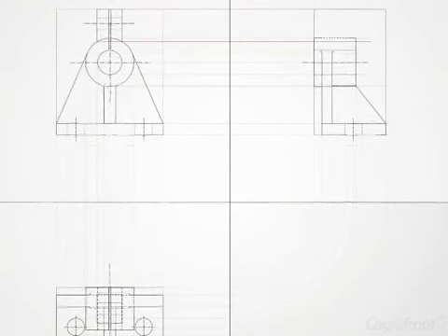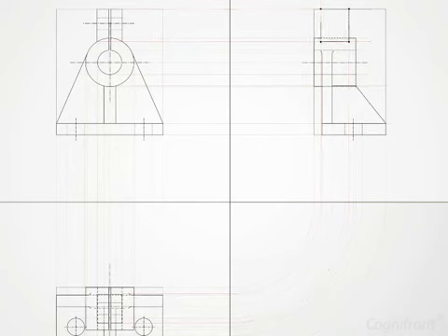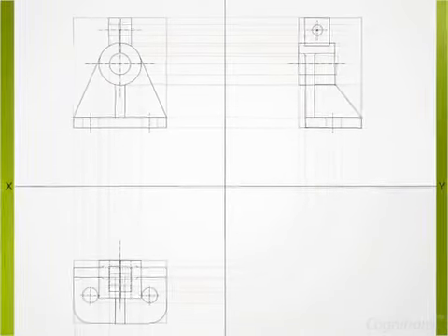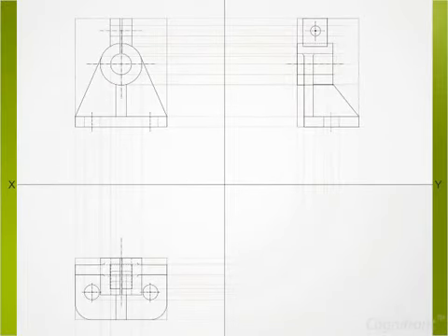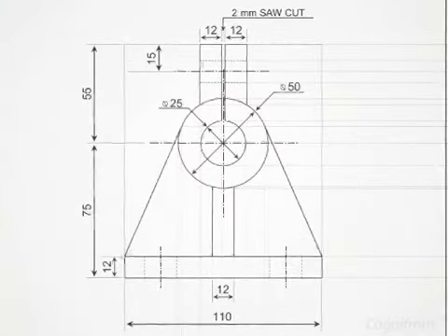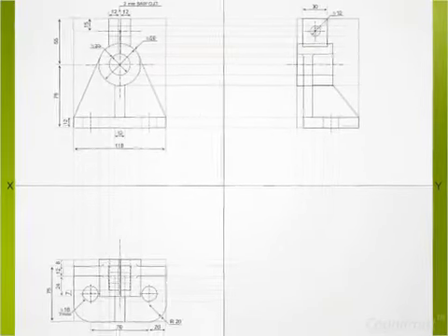Next, the block on the top of cylinder should be generated. Also, observe that we will have to show hole that goes through this block. So here we are with all the necessary details sketched within the solution. Now it's time to show dimensions of this object in all required places. This is how we have solved the problem of projecting this bracket object in front view, top view and side view.